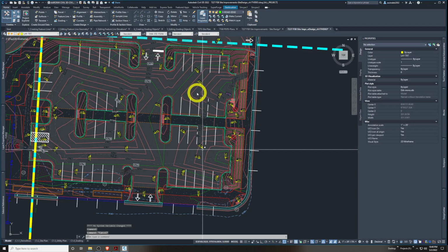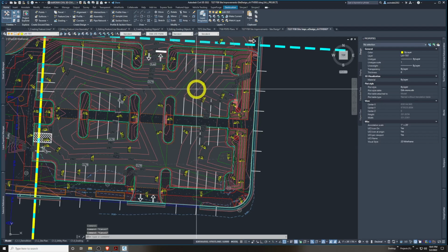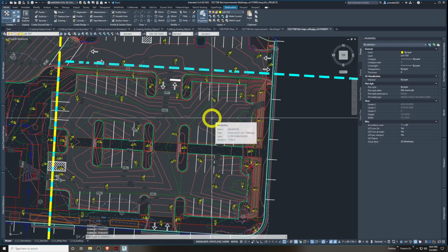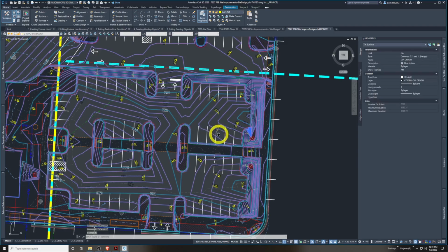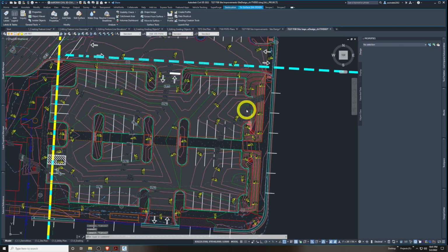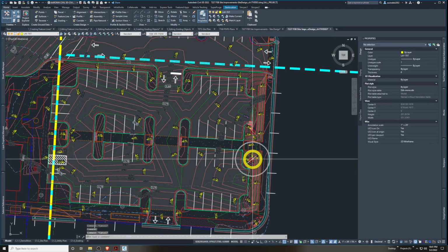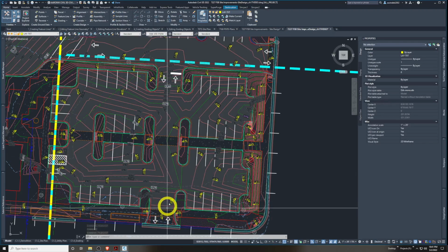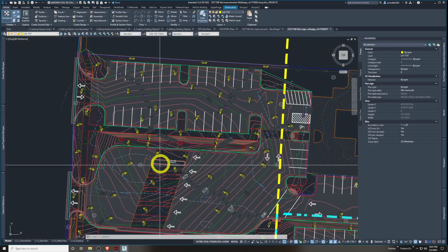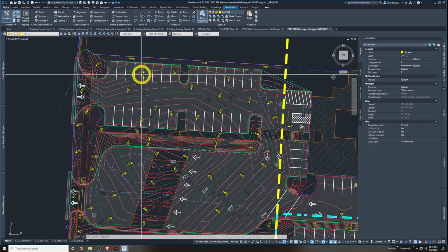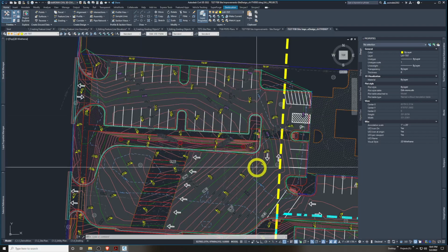And keep in mind, this surface that I have established is very exaggerated. It's 0.2 to 1 foot contours to really show it. It's fairly flat, but I have a low point here, draining into here, low point, sumps here, low points. I have a lot of entrances on various sides of this site. Another low point here that drains into here, drainage this way.